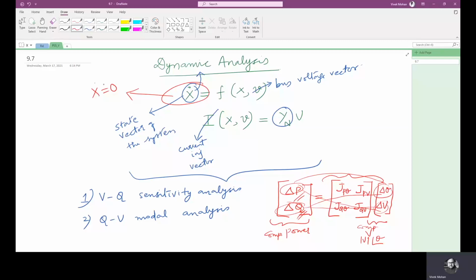Corresponding change will reflect on V. Such curves are generated by executing a large number of power flows, or several power flow executions are done, to draw such curves using conventional models. These procedures can be automated, but they are time consuming and they don't readily provide the information useful in gaining insights into the cause of stability problems.